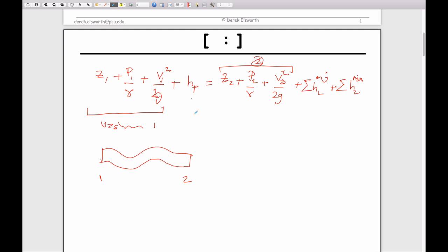Pump head we define as being power, which I've used the terminology W dot. Work is Newton meters. Rate of doing work per second is power, watts, named after that delightful Scotsman. And it's divided through by, you can write it in different ways, unit weight of the fluid that you're pumping, multiplied through by the volumetric flow rate. We've always used Q. And of course Q would just be equal to what? Velocity times area. Or equivalent. So whatever Q is in the system.